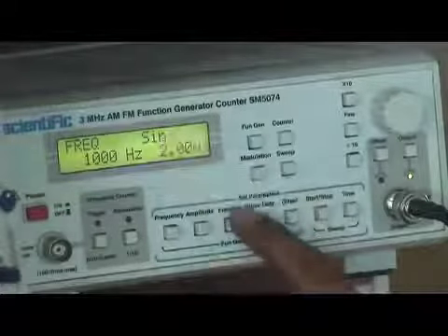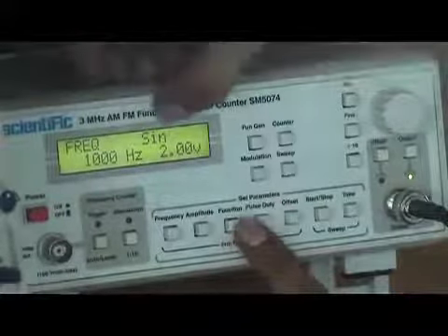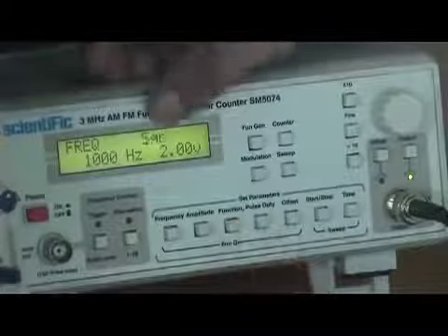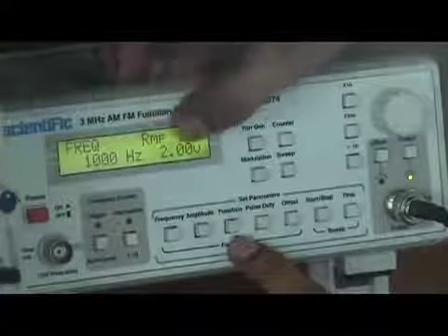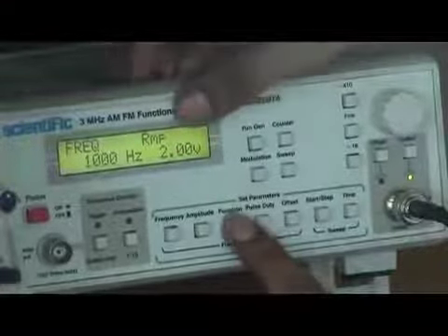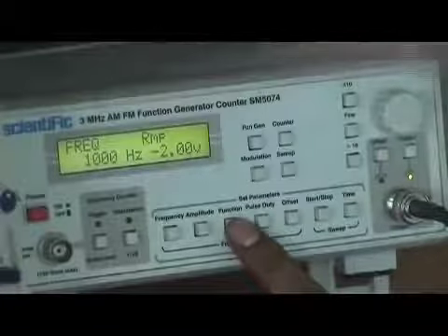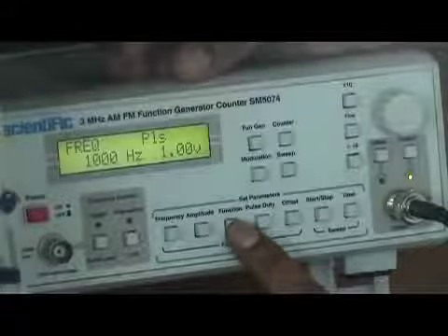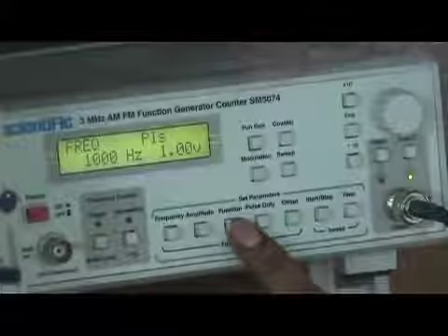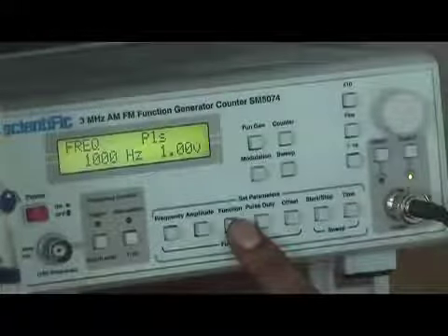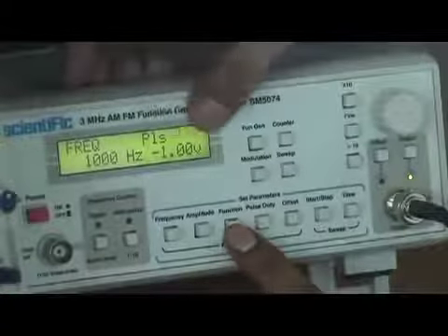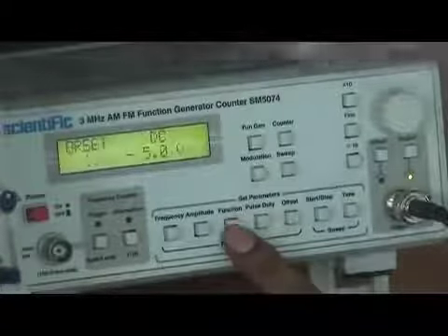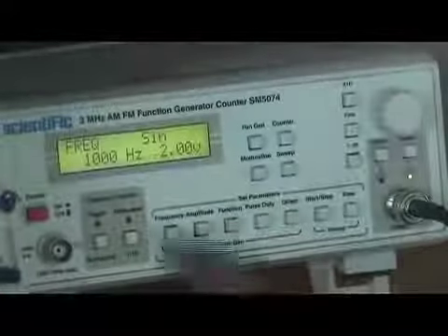Now what is the function? My function is sinusoidal. You can change the function from sinusoidal to various functions like triangular. If you press it again, square. Press again, it is again a square. Ramp, it's 2 volt. Ramp minus 2 volt means a negative ramp. This is pulse 1 volt, because when we say pulse, it denotes only from reference to upper level or reference to below level. When I press it again, it says a pulse but minus 1 volt, means below. Then a DC voltage, then again back to the sinusoid.